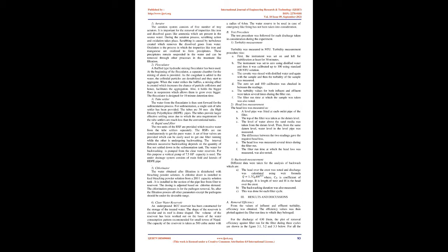Rapid sand filtration is a purely physical treatment process which can be explained by two physical principles, mechanical straining and physical adsorption. Firstly, mechanical straining. Larger suspended particles get stuck between the sand particles as they pass through the filter media. Secondly, physical adsorption. Smaller particles adhere to the sand particles due to the van der Waals force of attraction. An additional chemical such as a coagulant or flocculant can be added to increase the adhesion process.